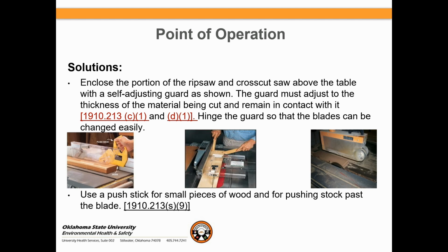Now, let's go to the other part over here. Use a push stick for small pieces of wood and also for pushing stock past the blade. These little push sticks, you can make them by yourself, or you can go down and buy some pre-made ones. Just depends on what you're looking for. If you take care of them, guys, they will last a long, long time. This is the type of device to actually push the wood on through. So that's point of operation.